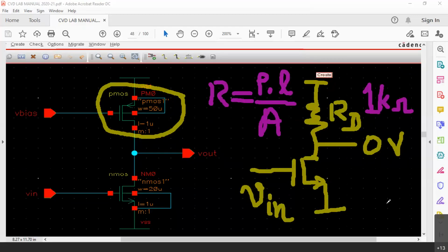It is not a very bad conductor also. Polysilicon is somewhat a conductor. But we have N well, again that is a conductor only. P sub, that is also a conductor only in one way or the other. Metal is now a very good conductor. So we should use those materials only for manufacturing resistors also, for manufacturing capacitors also inside the chip.